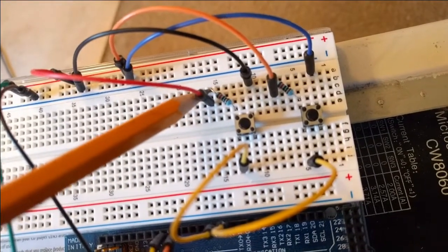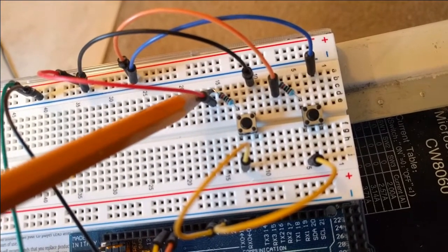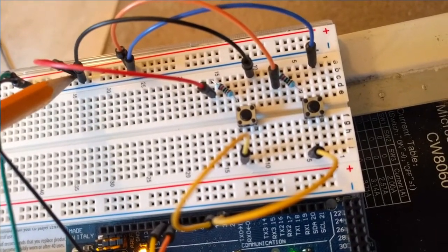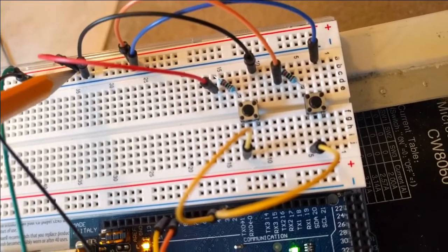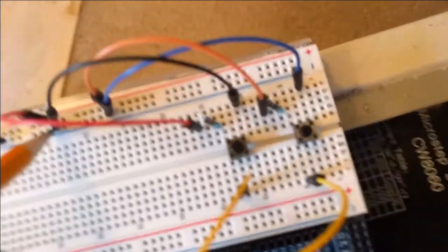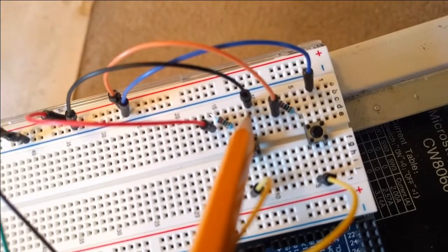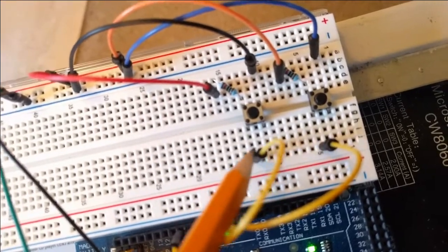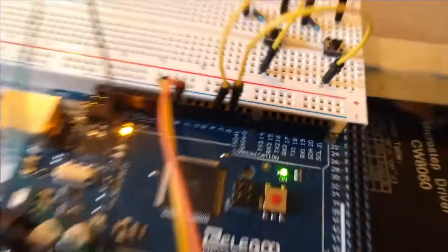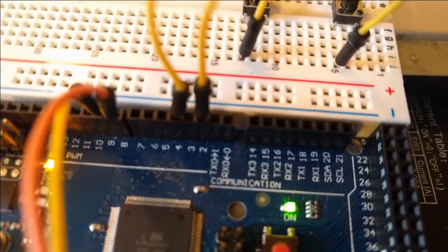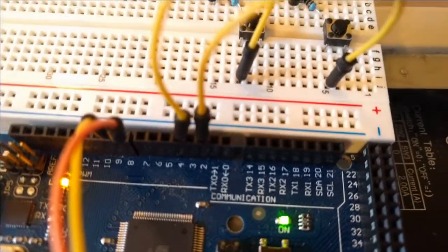It connects with this, so this is in line with the 10K resistor, and that comes from my power board, the power strip. It's tucked in here behind. There you go. And then this is my negative, which goes to here, and that's that side of the switch. And then this pin goes up and over into my number 4 on the Arduino. So if you're following the code along, you'll see that that is the button direction state.